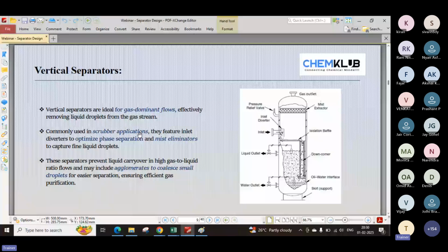Sometimes you might have seen that the feed is majorly gaseous, but still the compressor has been given with a separator. In those cases, you have to consider 2 to 4% mass basis of incoming flow as your liquid volumetric flow entering the system. This 2% criterion generally comes from the flare knockout drum sizing as per API 521.